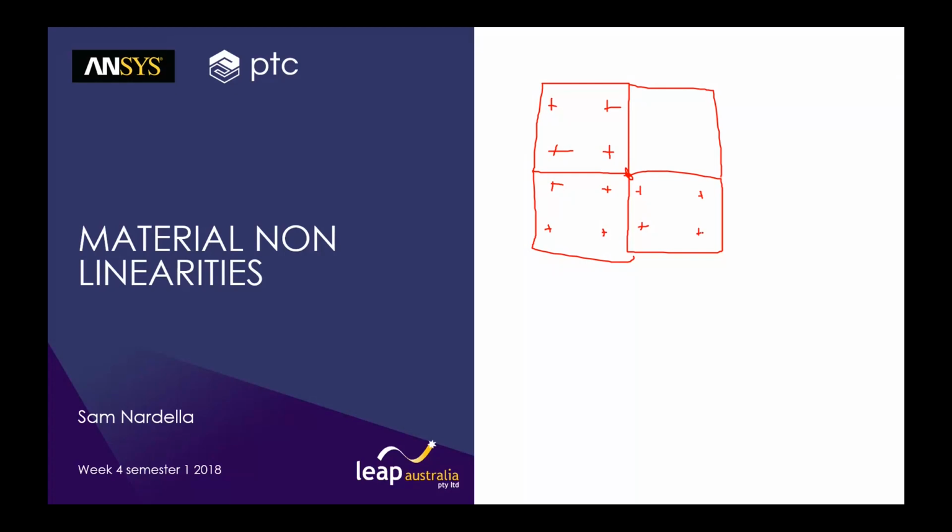So when you have metal plasticity, each one of these plus signs are the integration points. So we calculate the stresses at the integration points, and then if it's an elastic stress state, the stresses are extrapolated to the nodes. So here you'll have 4 values of stress.